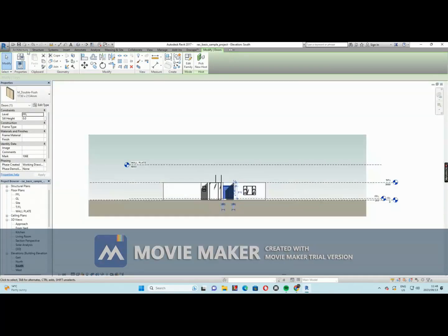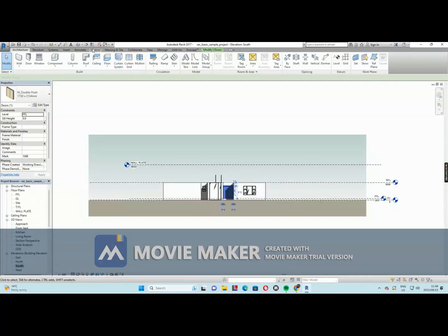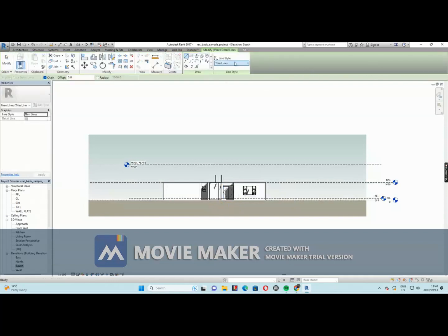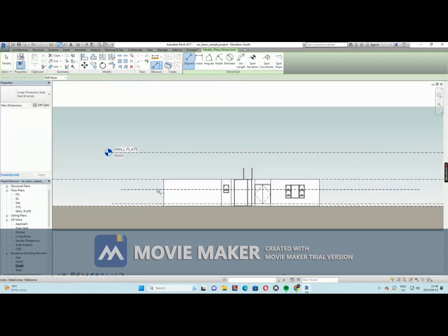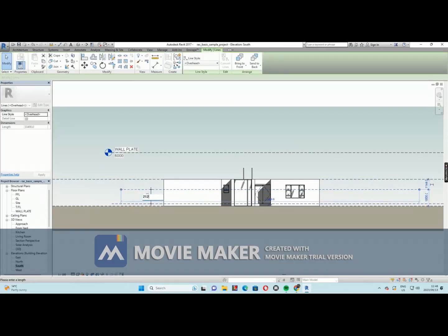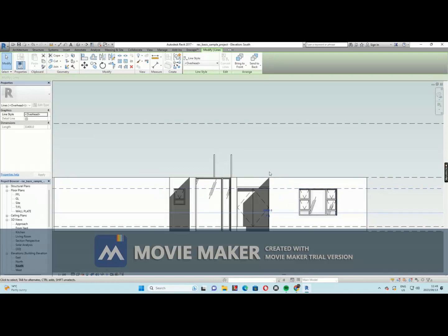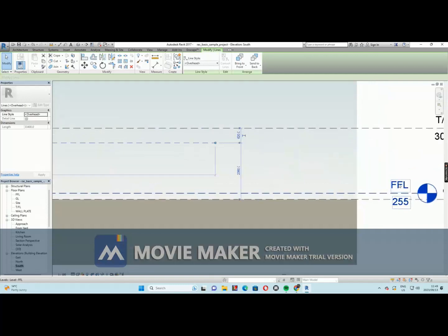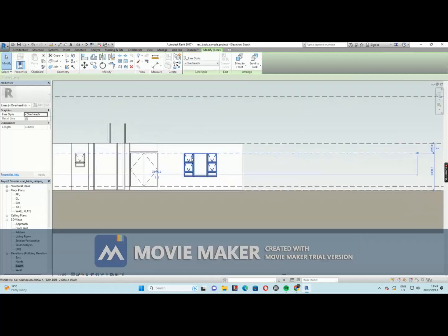Just a thin line or an overhead line, just for your window level, because let's say my window level is at 2.1. I want it at 21.25. You see, all my windows, they are there, because I put them on the first, finish the first floor. They automatically go to 2.1. Just for the sake of checking.